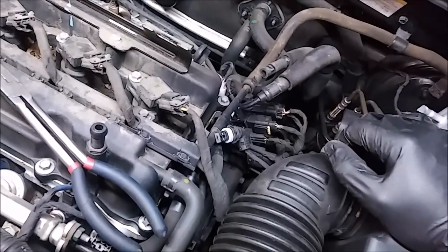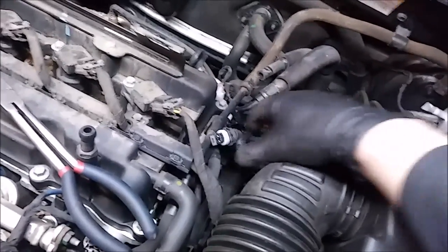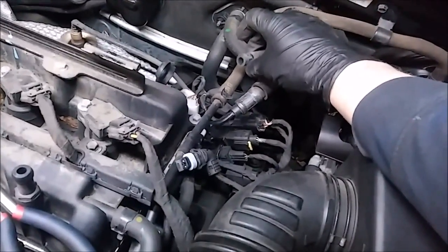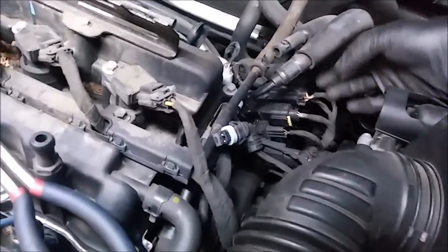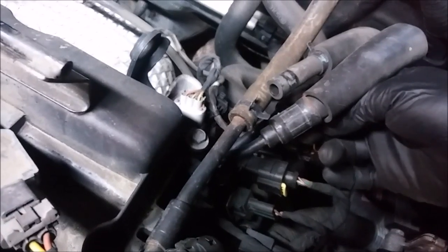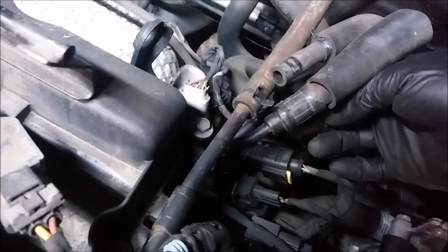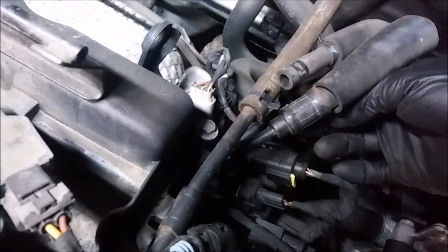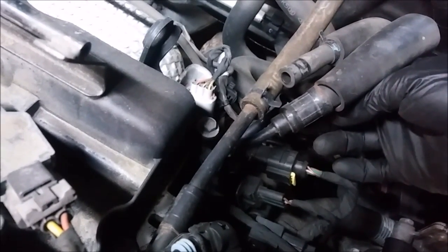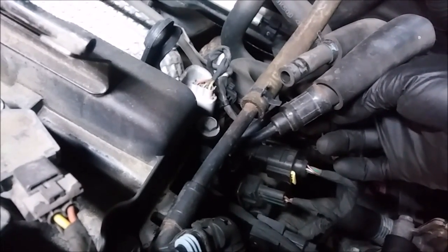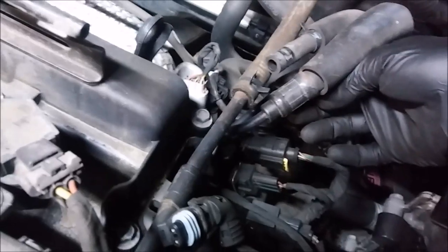Alright guys, so for this purge solenoid quick test, all I've done is I've disconnected this electrical connector, and I have the hose going to the tank side of the purge solenoid disconnected. I'm just reaching around this hose, and there's a little metal pipe back here that comes from the purge solenoid. I'm just sticking my finger over it. I'm feeling for vacuum. I currently don't feel anything. So that's a pretty decent test for the purge solenoid. If you have a purge solenoid that's leaking, you'll usually catch it with this test.